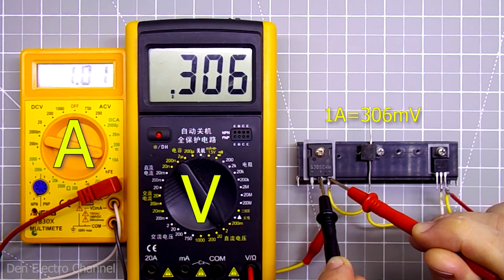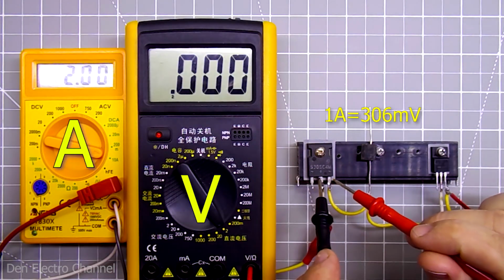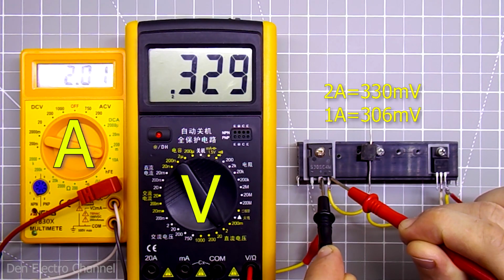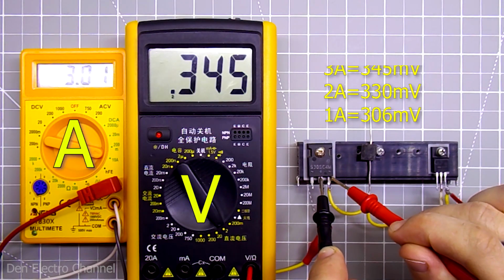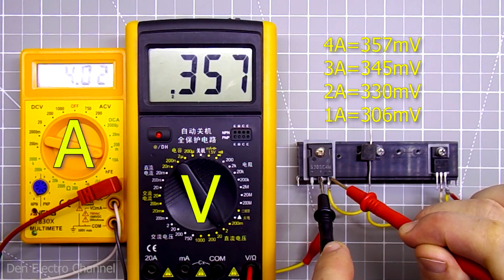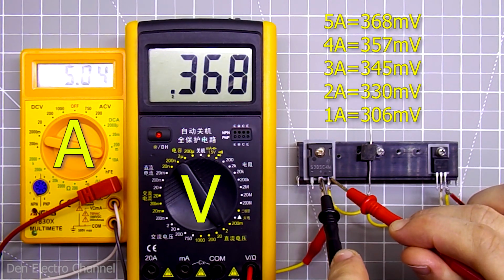The voltage drop was 306 millivolts. I increase the current further. I will set 2 amperes. The voltage drop becomes more than 330 millivolts. With a current of 3 amperes, the drop is 345 millivolts. At 4 amperes, 357 millivolts. And at 5 amps, 368 millivolts.